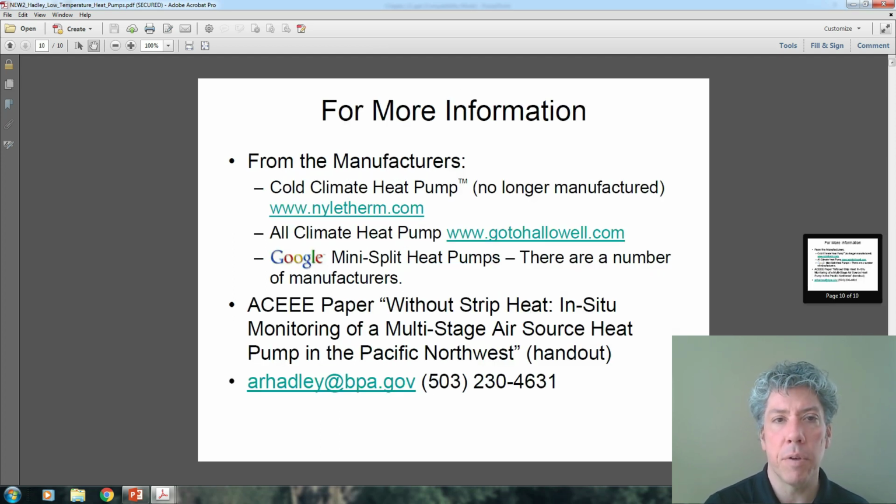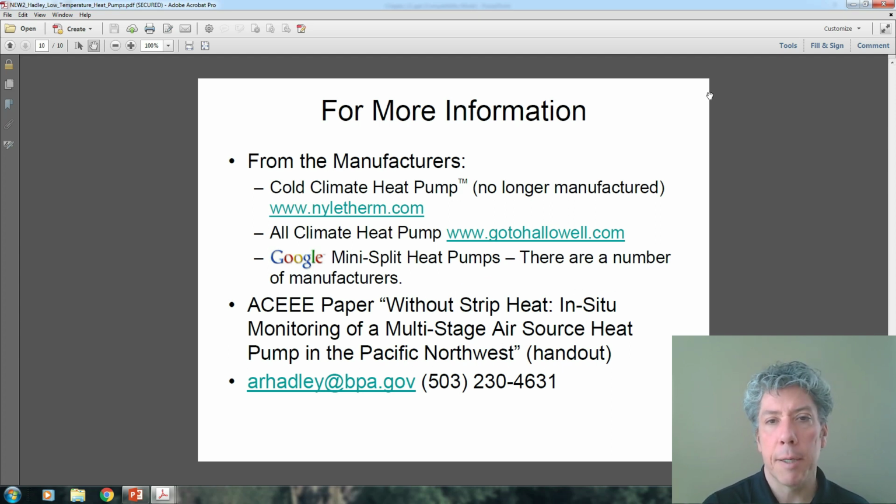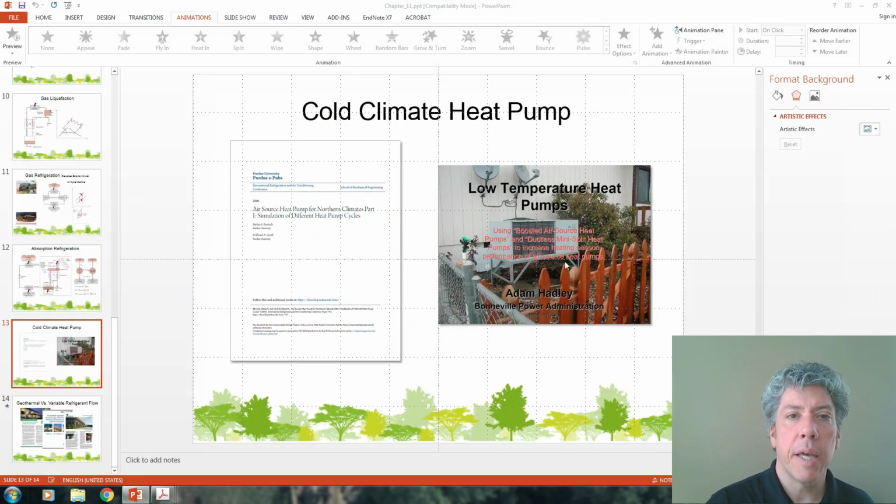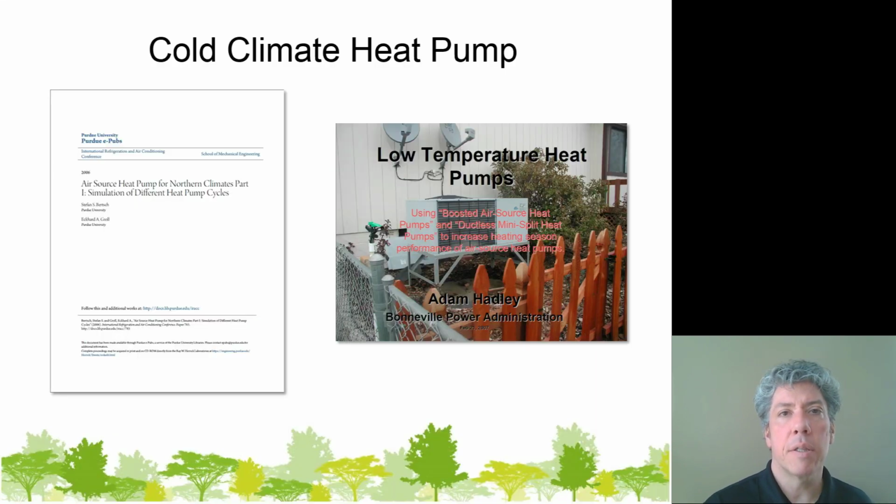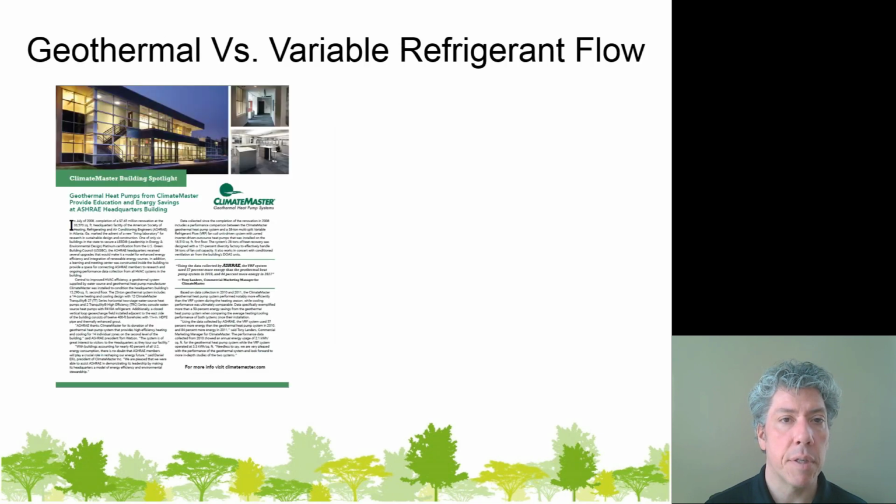I've got a few links on this. If you're interested, there's a paper written. Unfortunately, these are no longer manufactured. They went out of business. The reason they went out of business, I'm sure, is that the Achilles heel of heat pumps kicked in. One of the things these devices would have to do is defrost the outdoor coil, and they'd have to do that often. By doing that, they lose a lot of efficiency.